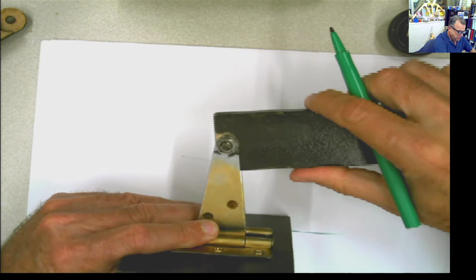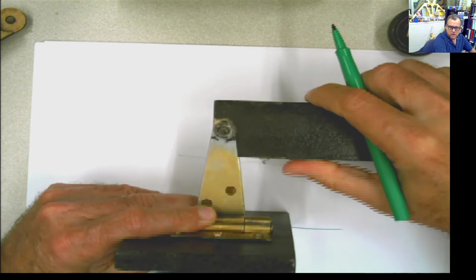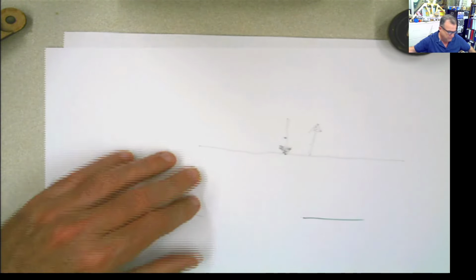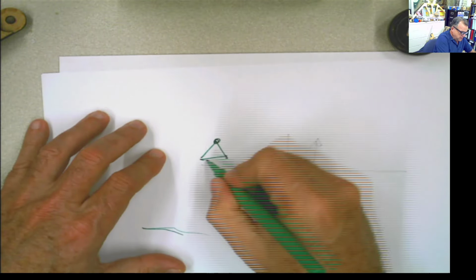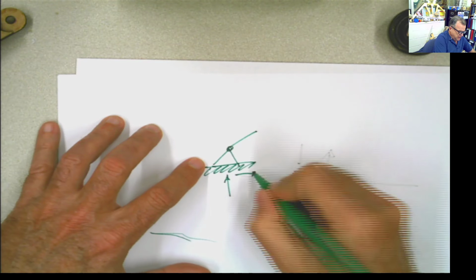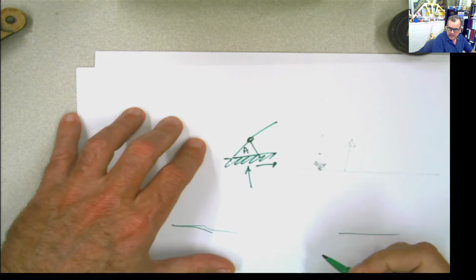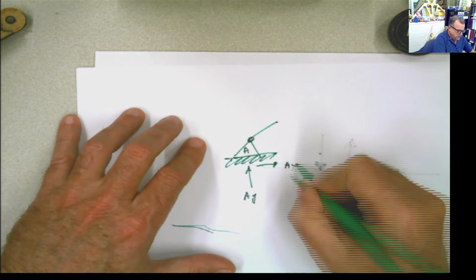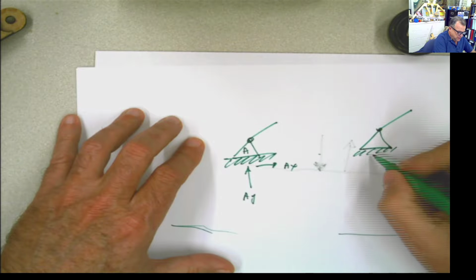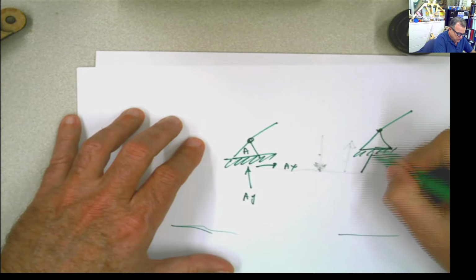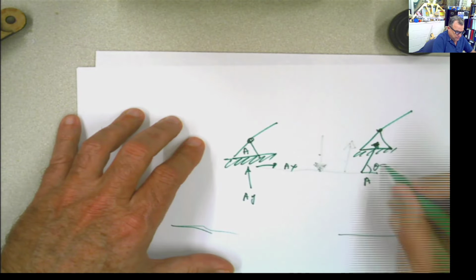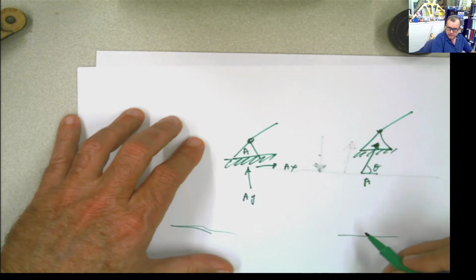However, if I take this and I try to move it side to side or up and down, it's not going to happen. So then the pin, which is that drawing that we had before, is something like this. The pin is going to provide either, you can say, two reactions, if this is the part A, two reactions, AY, AX, or you can say also that a pin produces only one reaction, A, but we don't know the angle. So one reaction with unknown line of action.